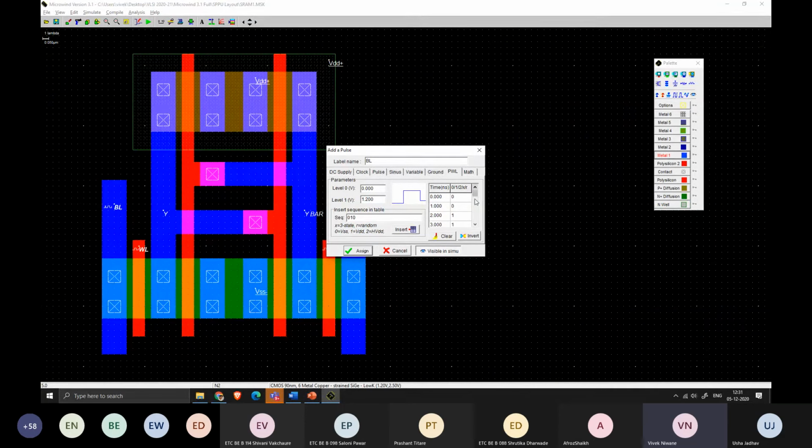What is happening is, from 0 nanosecond going up to 3rd nanosecond, we are writing the data, and from 4th nanosecond to 5th nanosecond, we are reading the data. Now observe over here. First 0 written, 0 written, 1 written, 1 written, and then we are going to read the data. So 1 was written at the last moment, so we will have 1 at the output.